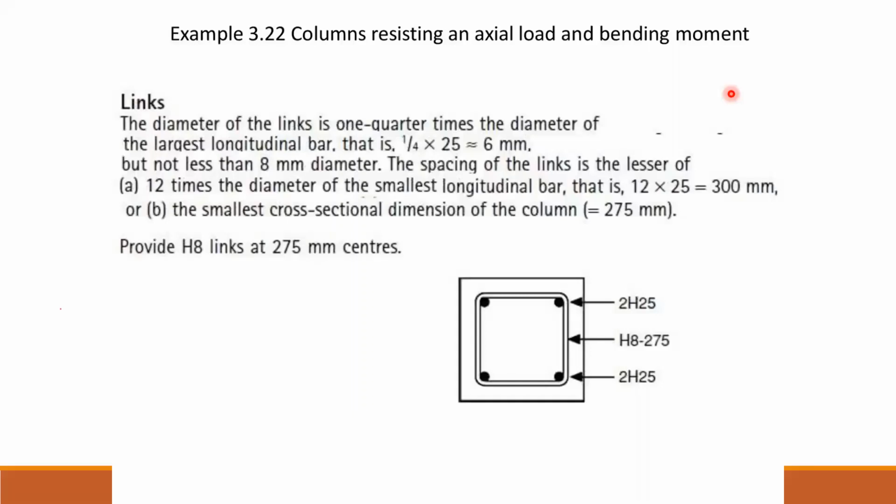Links, the diameter of the links is one quarter times the diameter of the largest longitudinal bar, that is 1/4 of the main bars.